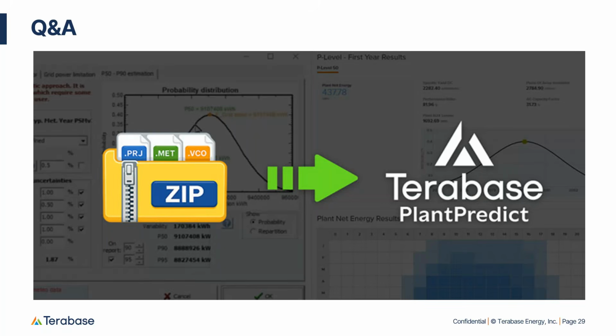In the meantime, one thing you can do is open this module in PVsyst. You can change one character of the name or the description, something that is not a numerical value. Call it, I don't know, module number 1 dash PlantPredict export. That way you can save it as a PAN file, and now it becomes something that is going to be exported with the zip file. So if you encounter this issue, that's the workaround we have for now.